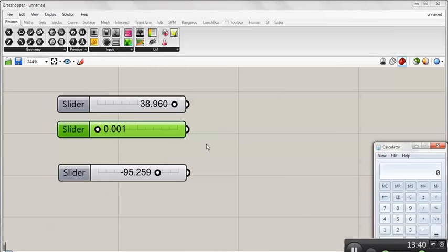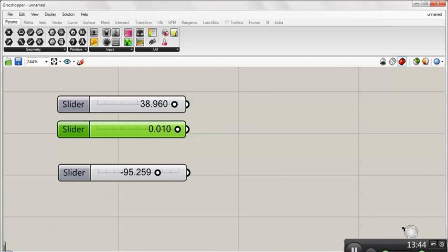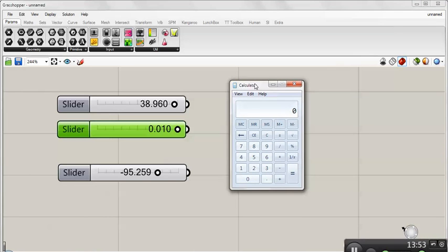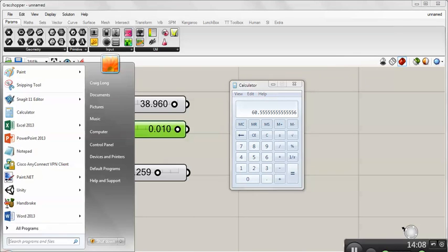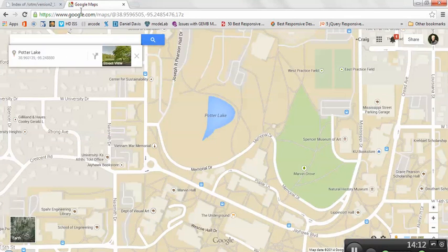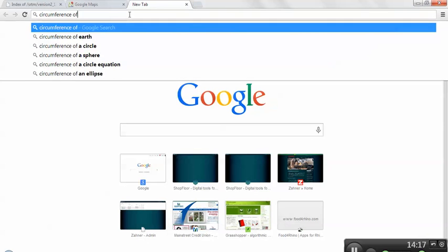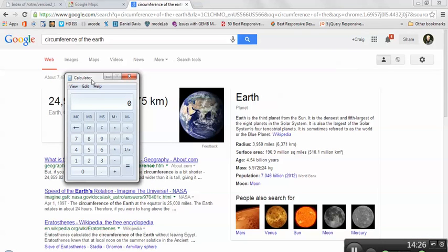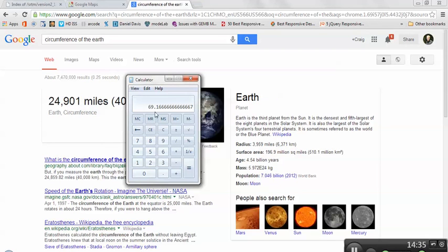And in terms of actual distance, 0.01 of a degree, the easy way to check this is, I can't remember exactly, I think it's 20,800. No. All right, ask Google when you can't remember. It's 24,900. So latitude, longitude is 360 degrees, so 24,900 divided by 360 degrees. That's where you get the 69 miles per degree. So we just set our range at what is 0.001 of 1 degree.